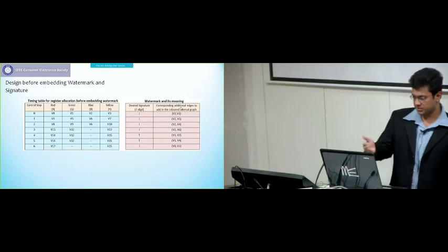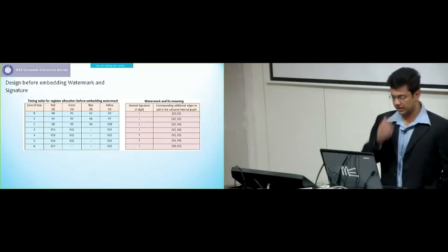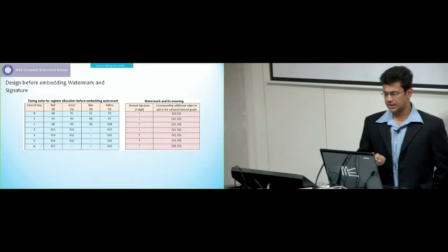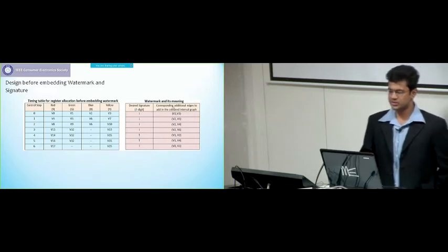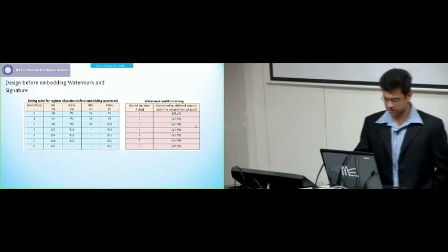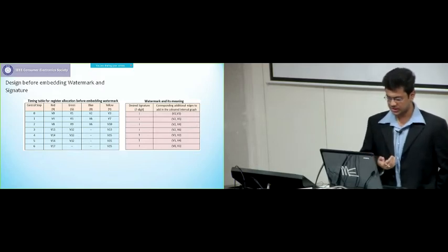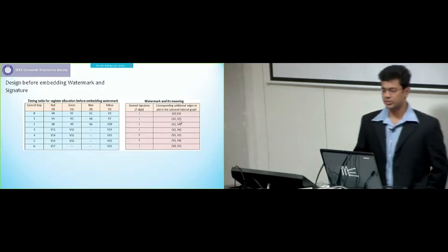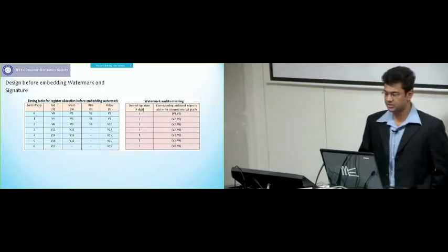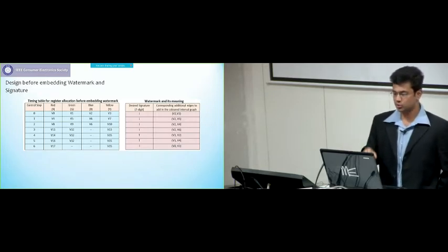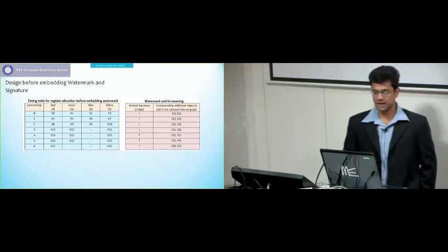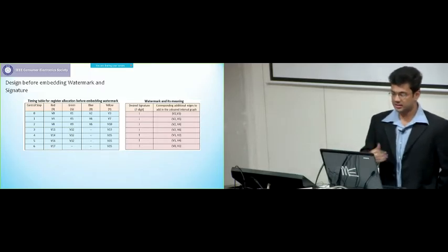I remember I was speaking about this in my last talk, so we can take a cue from there and understand how this is decoded. I am not going to go into details on this today, because we have already learnt about this in the last lecture. Now, what this indicates basically is that there has to be an additional edge between two variables, which is V2-V3, V2-V5, V2-V4, V2-V6 and so on. These external edges indicate that these two variables cannot be allocated to the same storage register. That means they have to have distinct assignments.